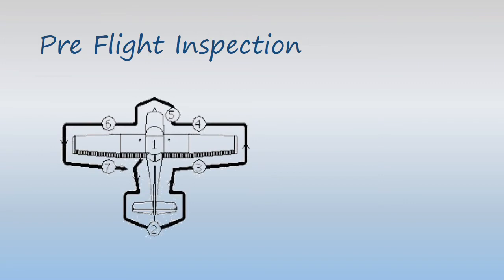As our first topic, now you can learn how to perform your pre-flight inspection. It's basically a visual check of your aircraft prior to your flight. At first you have to reach your aircraft and open the left side door, where the pilot in command sits in the aircraft. Then you can have a visual check of your cabin and the instrument panel for loose fittings and broken parts.